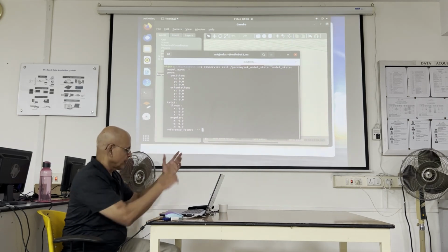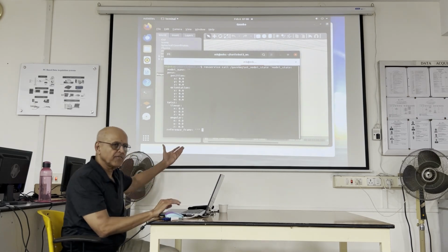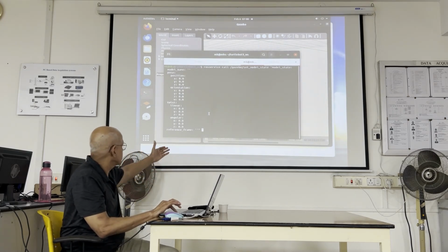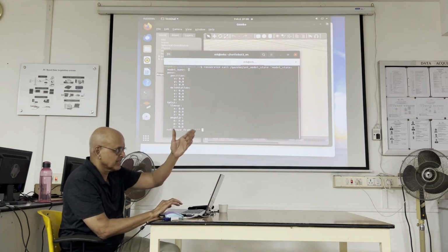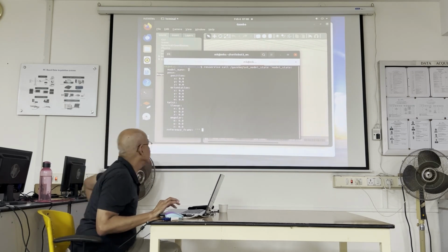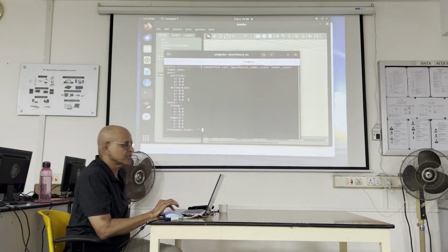Anyway, I showed you this, but there's no point since it's not working. Essentially, when it works, what you're supposed to do is put in world here, or world frame, and then put in the model name, turtlebot3 underscore whatever, gazebo whatever. I forget. We put it in there, and it zeroes out the velocity. I'm sorry, it zeroes out the position.